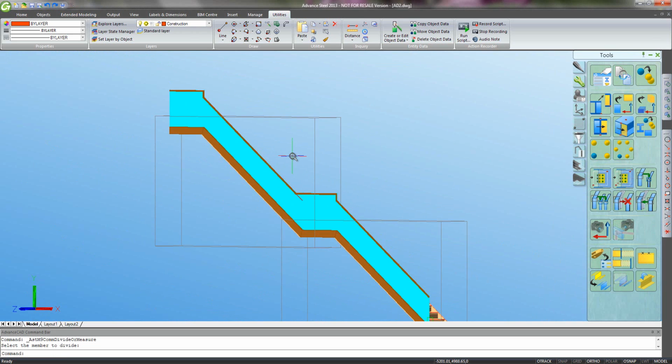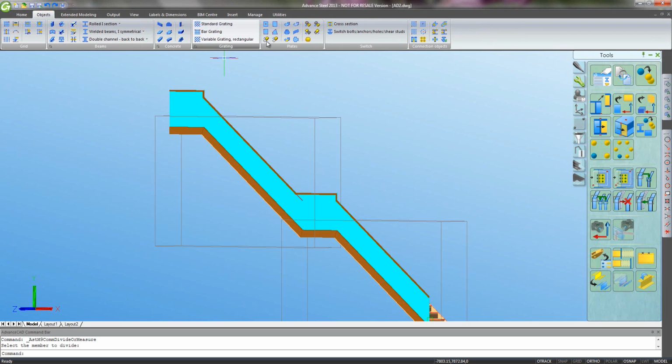And now I can use those nodes and the corners of the plate as positions to cut from. So I can use the various commands we have to split the plate up into separate sections. I'd like to add a gap of 10mm between each pair of plates, so set that option, and now I can choose the point I want to cut at to divide the plate up. So I do that once for each cut.